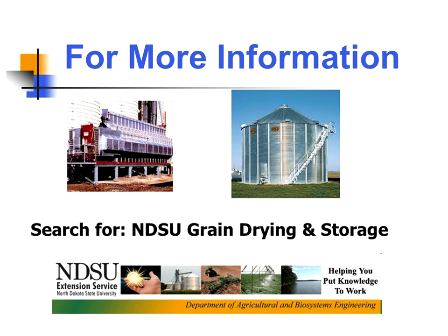When we start looking at a high temperature dryer, temperature and relative humidity does have a little bit of influence, but when we're taking outside air and heating it to 200, 230 degrees, the effect of the outside humidity ends up being fairly minor, and so typically isn't a major consideration when we're talking about high temperature drying. Hopefully that answers the question.